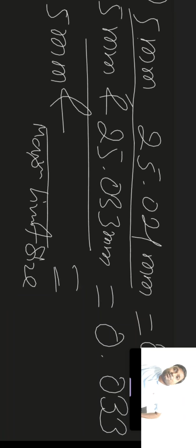If you have observed, from IT6 or IT5 to IT18, all the tolerance grades are arranged in a preferred series, that is, each succeeding IT value is obtained by multiplying the preceding IT value by approximately 1.6.